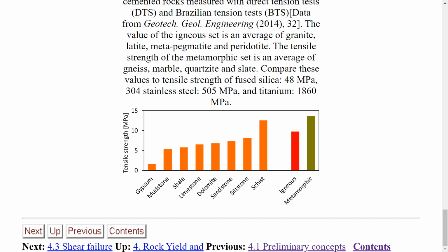So if you had, like, similar to this rock, a 1 inch square, this is less than 1 inch square, you could hang 750 pounds from the rock. So that's to give you an idea of the tensile strength. It looks like a lot, but actually it is not. Compared to other materials like steel, in which you see the number over there, the tensile strength of steel is 500 times more. And the tensile strength of titanium is about 400 times more. So the tensile strength of rock is not a lot, actually.